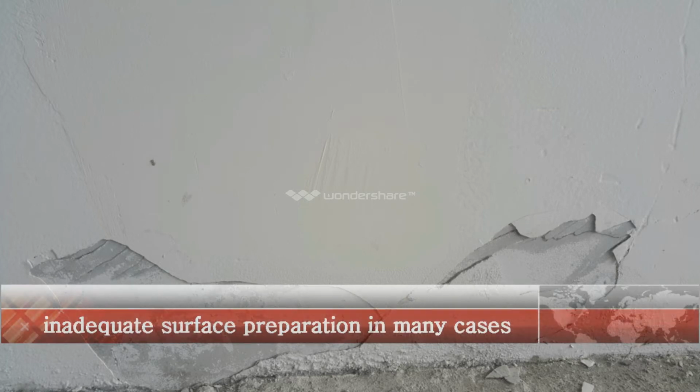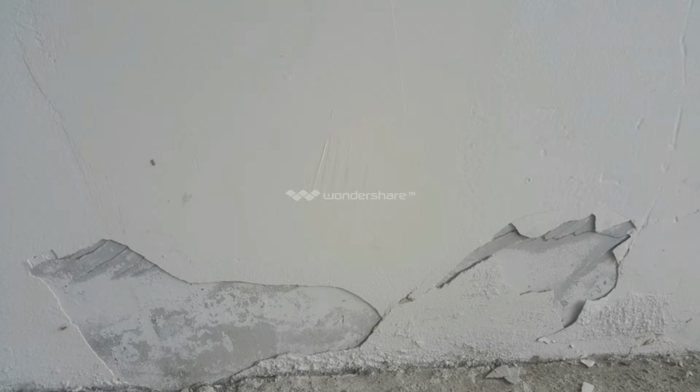The failure can be the result of inadequate surface preparation: not removing greasy contaminants from the substrate, not removing loosely bound substrate contaminants such as wind-blown dust and dirt or mold, and not removing substrate breakdown products such as weathered timber fibers, old powdery weathered concrete, efflorescence on concrete, and metal corrosion products.